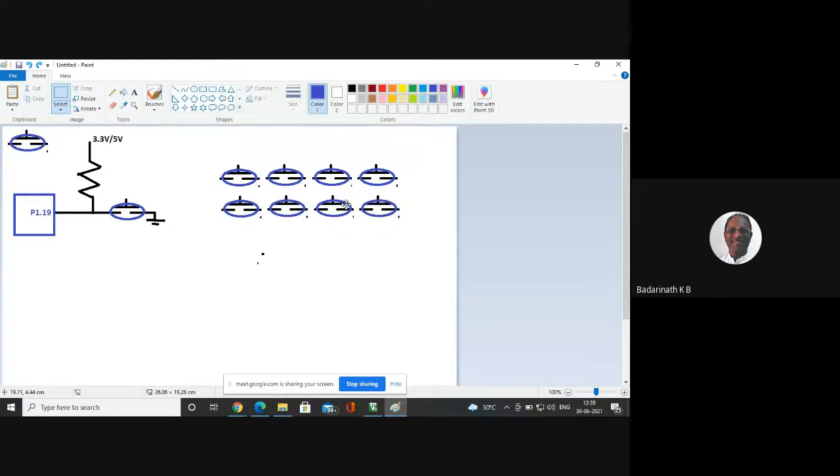Now look here. I have placed one row. I'll call this a row because multiple things are there in a single line. 4 keys I have placed. In the second row I have placed another 4 keys. Like this I can arrange. In a given line, I need not always have 4. I can have 2, 6, 8, anything is possible. Now I have taken an arrangement of 16 keys, since 16 keys are very commonly used in projects.